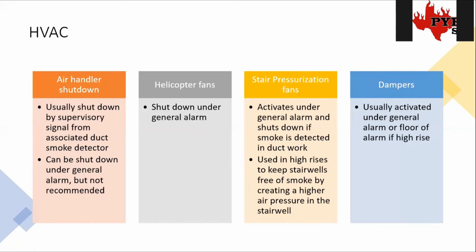It can handle the higher current. So sometimes on helicopter fans, you'll have to do something like that. Sometimes they actually have some kind of VFD controller that has an alarm shutdown. When they have that, we can use just the addressable relay, and we don't have to use an addressable to power a stronger relay. But that's going to take some on-site coordination to figure out what type of fans, what type of controllers they are using on that job site.